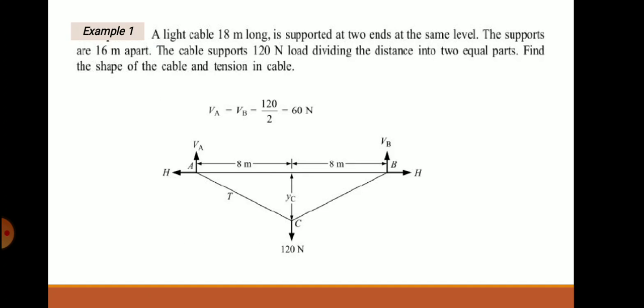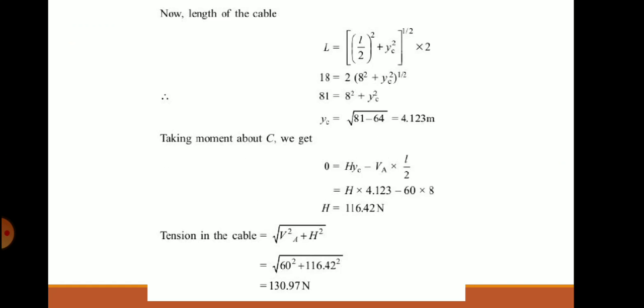How to understand this? See at that support point, what is V, what is H, then what is T? That is the concept of resolution. You can use the concept of resolution and find the tension in the cable. So if you solve this, you can evaluate the tension in the cable. So this problem is completely solved using basics of mathematics. One is the Pythagoras theorem, then taking moment about C, that is the equilibrium equation, then again the Pythagoras theorem. Using the same concepts you can analyze the problem.